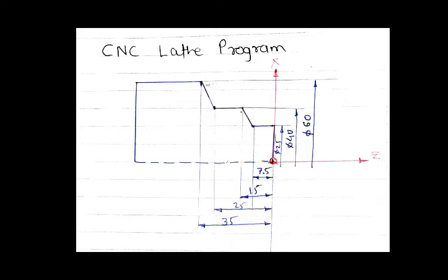And then the coolant control: coolant on, coolant off, whether the coolant is flood or mist. After that it needs the tool control operation, that is tool and tool parameters. Then the cycle functions, the type of action required. And last, the miscellaneous control, that is spindle on/off, direction of rotation, stop, or part movement rotation.